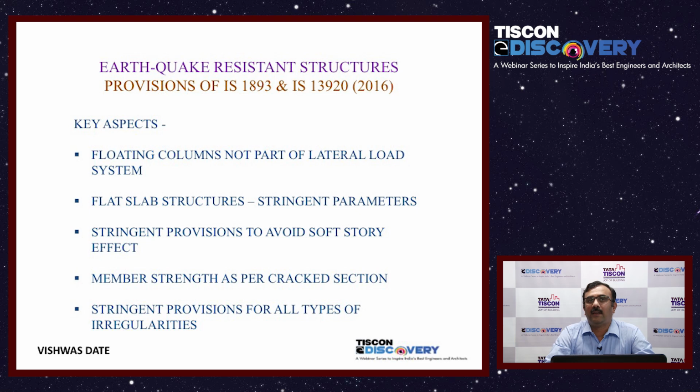Member strength in analysis today is considered as the whole cross section, which will be reduced to cracked section. Why? Again, because during an earthquake, or even before an earthquake, some members might have developed cracks because of tension. These members will not have the whole section available for your design. And especially when an earthquake starts, during the first few seconds it will reach the peak response. And if there is cracking in columns or beams at that moment, then they will not perform the same for the next 1.5 minutes of the earthquake, and will not have the same kind of stiffness to offer, which has been recognized. It was always there in international codes. It's just that we have started recognizing it today and putting it in the code today.